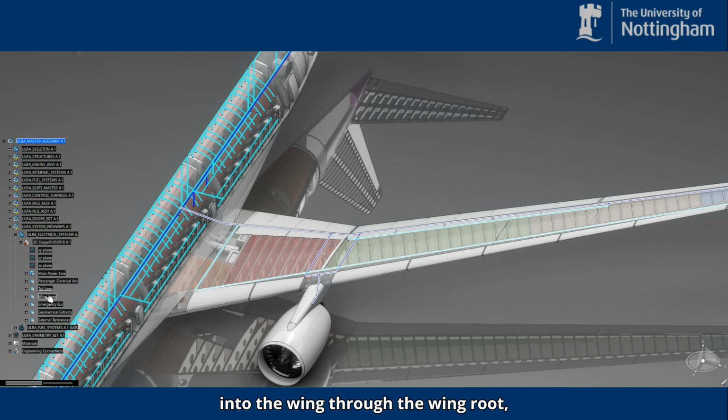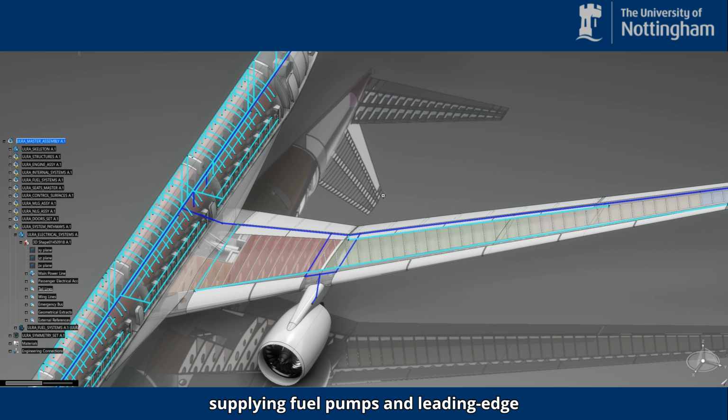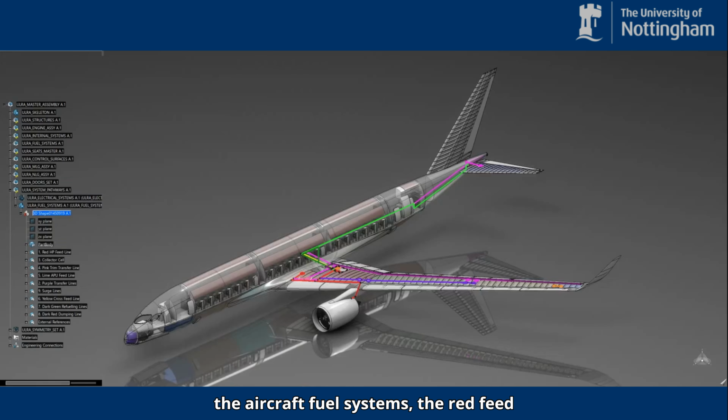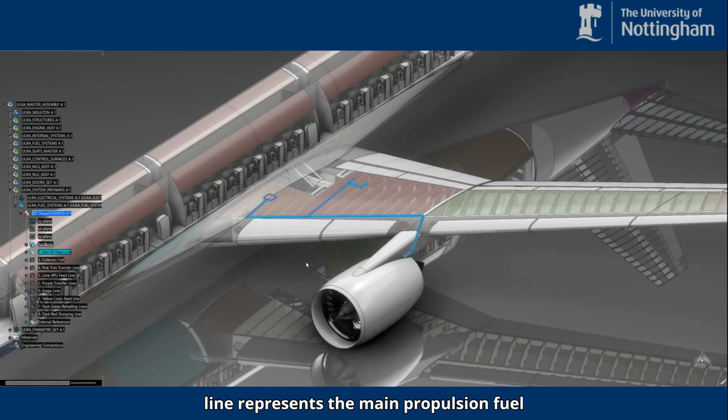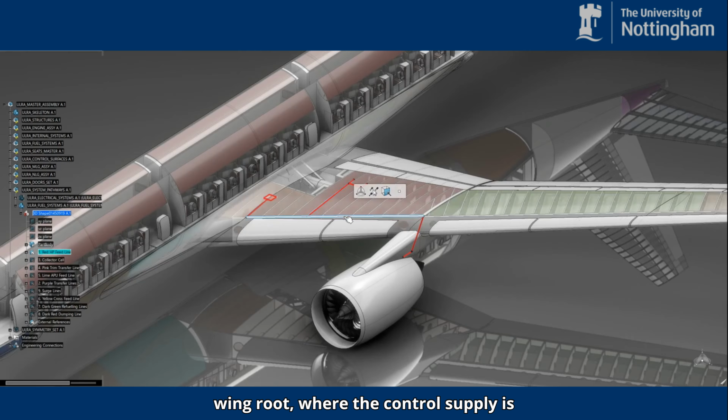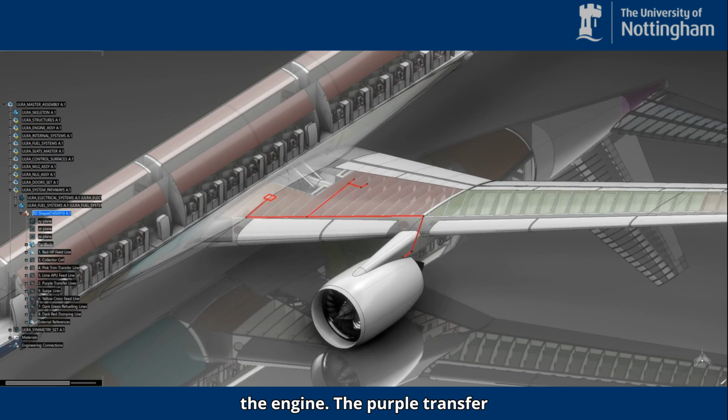Power is also routed into the wing through the wing route, supplying fuel pumps and leading-edge systems such as anti-ice through a span-wide distribution line. Moving on to the aircraft fuel systems, the red feed line represents the main proportion of fuel path. Fuel is delivered to the engine from the inboard collector region and the wing route, where the control supply is stabilized before being sent onward to the engine.